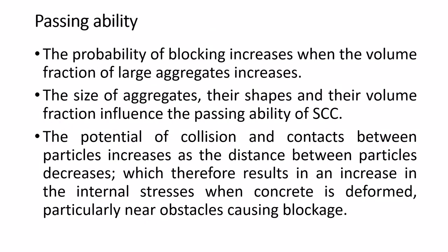Passing ability. The probability of blocking increases when the volume fraction of large aggregates increases. The size of aggregates, their shapes, and their volume fraction influence the passing ability of SCC. The potential of collision and contacts between particles increases as the distance between particles decreases, which therefore results in an increase in the internal stresses when concrete is deformed, particularly near obstacles, causing blockage.